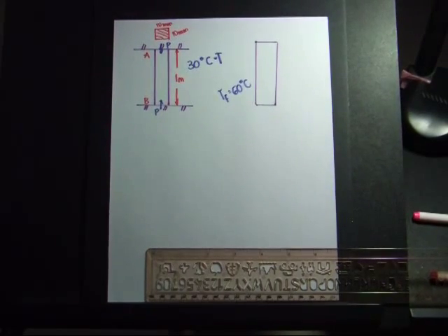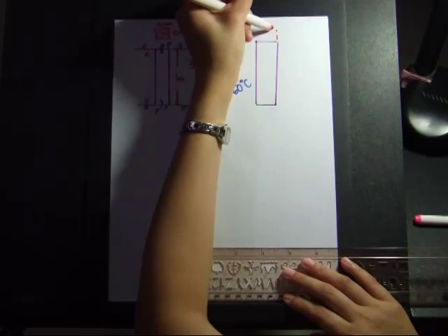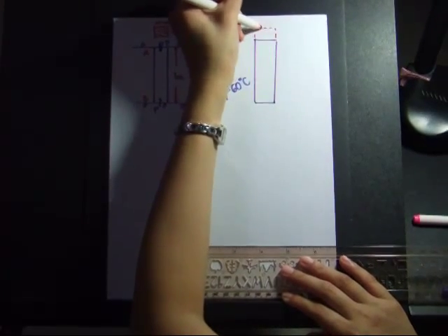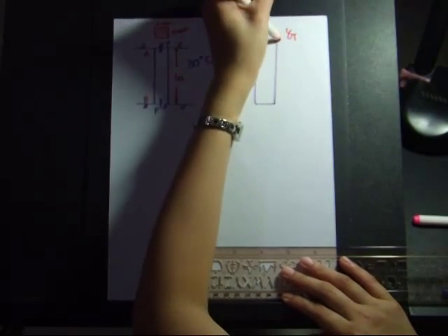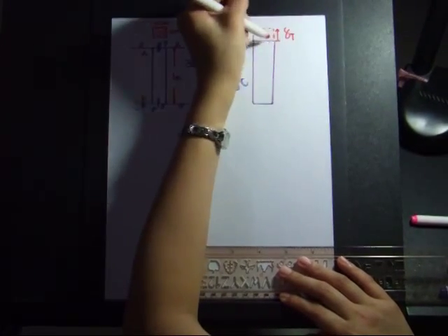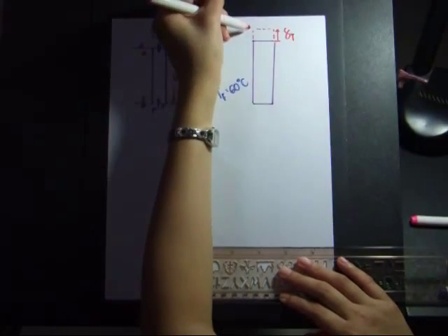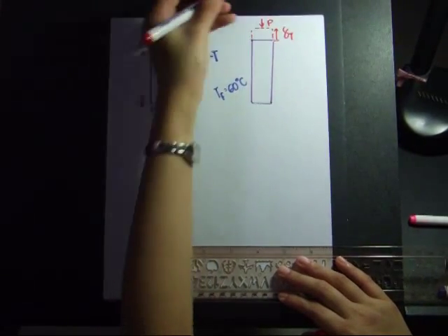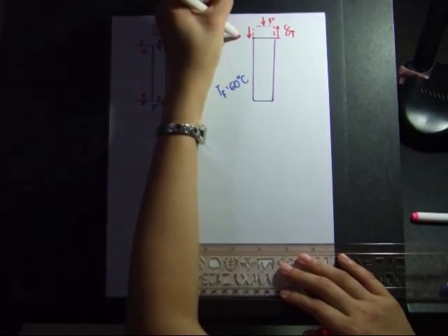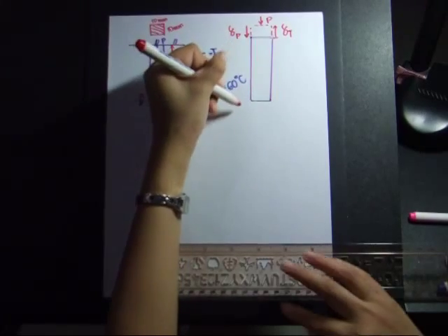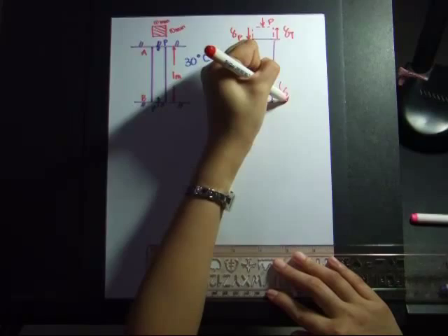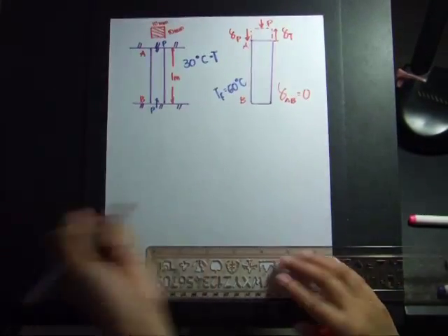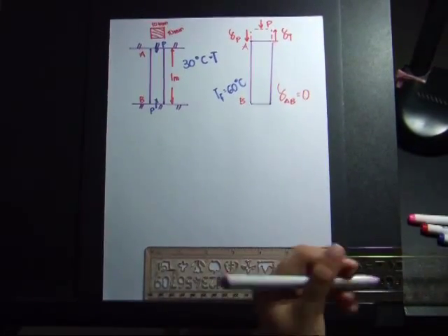Since the temperature rises, the material will experience expansion, and there will be thermal displacement at the top support, and it is counteracted by the force F that would be required to push the bar back to its original position. So this is our bar AB, so that means that the deformation of the bar AB is equal to 0.